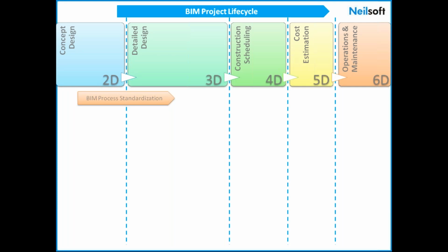So that is where our methodology is to first standardize your process, make sure we understand what are the different assets that you would be creating. So the assets could be the templates that we are going to create in Revit, or the Revit families, or the content that we are going to create. And that is where understanding your requirements, understanding what kind of data we want to maintain. Also, when it comes to Revit content or the families, at what stage, what kind of level of detail, or LOD, which is the terminology commonly used, is going to be required, whether we want a very detailed model at 3D level, or as we go to 4D, 5D, what kind of LOD is required.